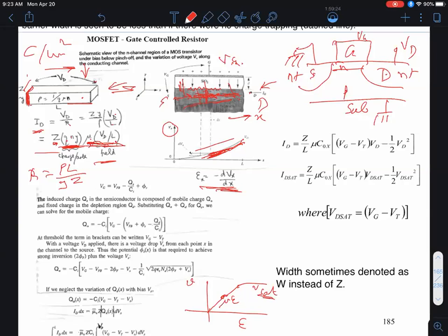Well, to do that, you have to look at the capacitance-voltage behavior of this MOS structure, which we discussed last week. Let me refresh your memory about that. So if it's a p-type silicon channel, if I have to plot the oxide capacitance as a function of gate voltage, we know for negative gate biases, you get the accumulation region. You attract holes. There's no inversion region, no depletion region. And you get a fixed parallel plate capacitor given by, sorry, this is gate.